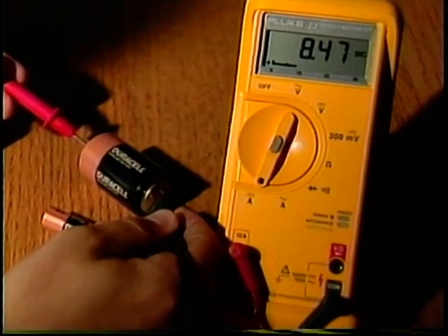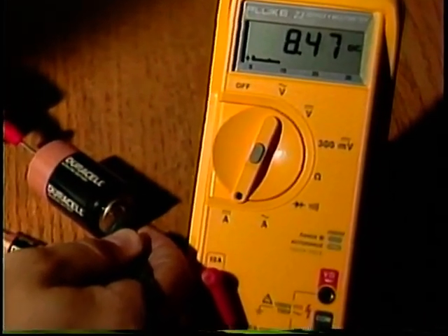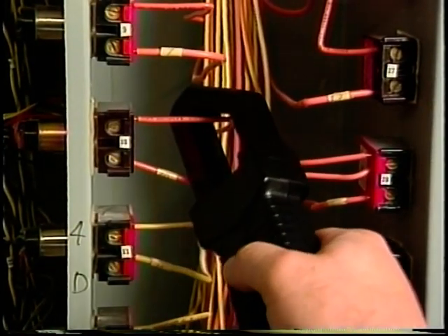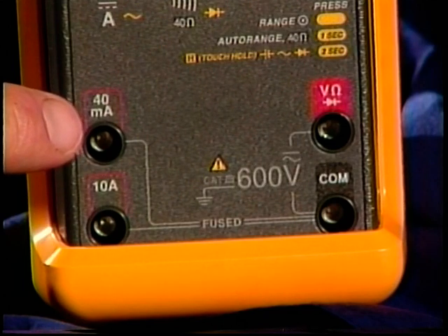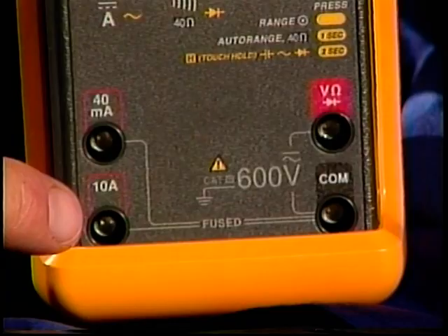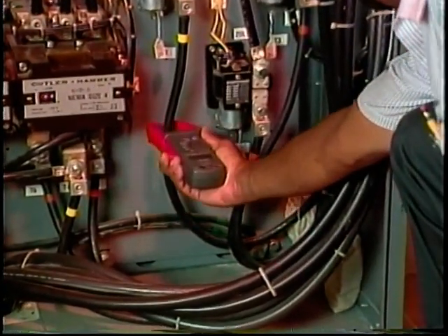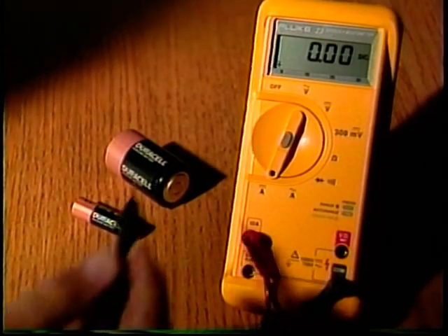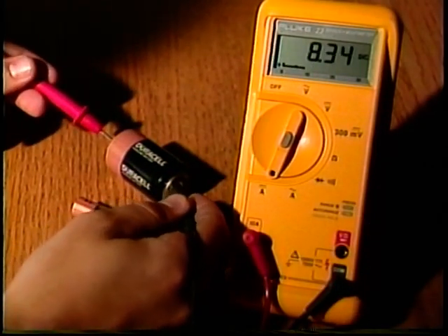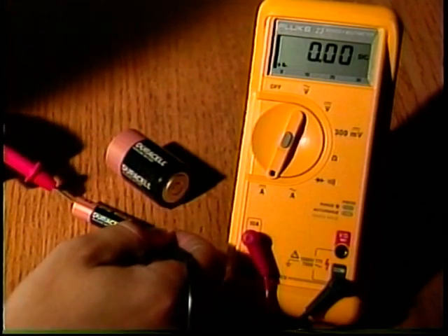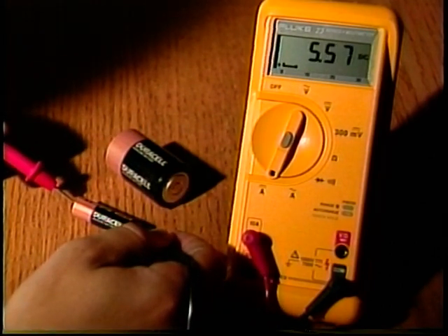Two methods used to measure current are inserting an inline ammeter in the circuit or using a clamp-on ammeter. The inline ammeter is used for currents that are less than the maximum current rating of the meter. Both methods are used when measuring AC or DC. An inline ammeter measures current in a circuit by inserting the meter in series with the component tested. Inline ammeters are primarily used when testing smaller electronic components.